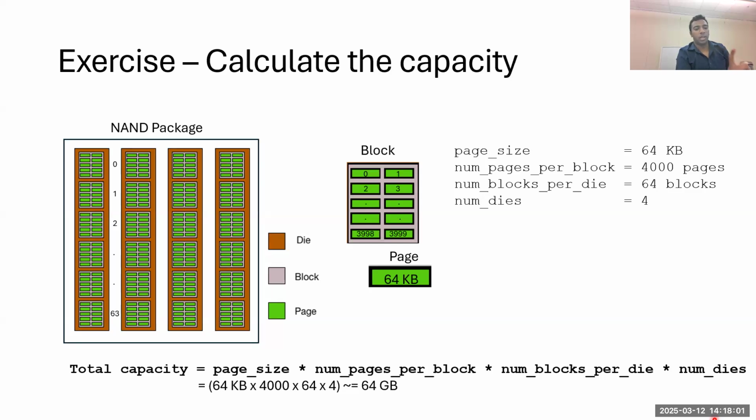And from figuring out that window, we will have to apply those algorithms to refresh the data in the drive. One thing to note here is the data center has a very strict and high requirement compared to the SSD that we have in our laptop. So the policy will be different for these two as well. In the data center, the data will be refreshed more so that the data reliability is much higher. For our laptop SSD, the refresh will be a little bit slower, I guess, because we can afford to have more cost issues or reliability issues in our laptop. Does that answer your question?